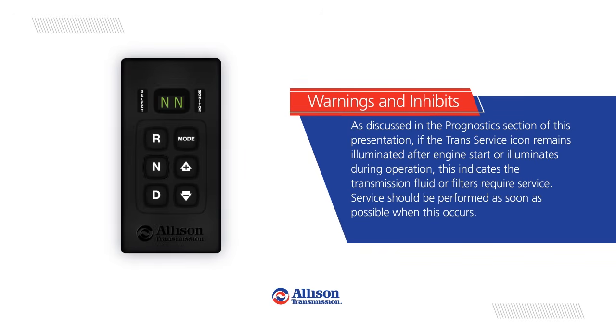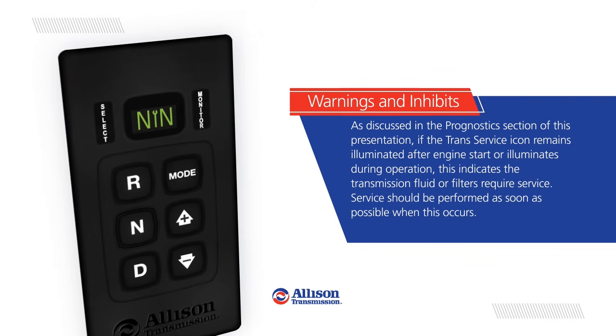Warnings and inhibits. As discussed in the prognostic section of this presentation, if the trans-service icon remains illuminated after engine start or illuminates during operation, this indicates that transmission fluid or filters require service. Service should be performed as soon as possible when this occurs.